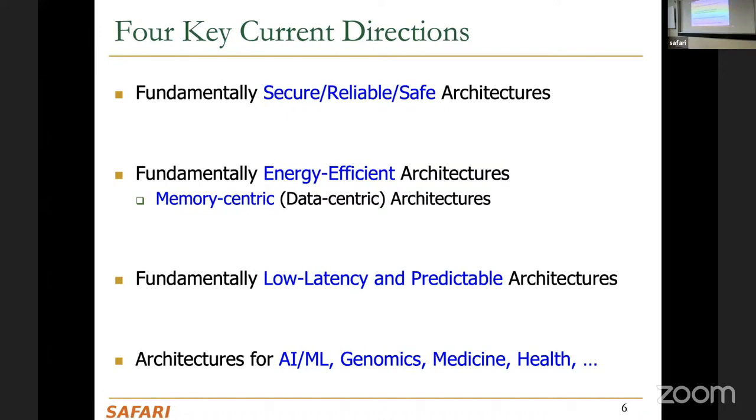Of course, you can combine these two paradigms. You can add some logic plus exploit the memory's computation capability, which I think should happen also going into the future. But that processing using memory is also very interesting and fundamentally more efficient because you don't add any logic to the computation. The question is, of course, at what things is this fundamentally more efficient and how do you make it work? So there are a lot of issues over here, right?